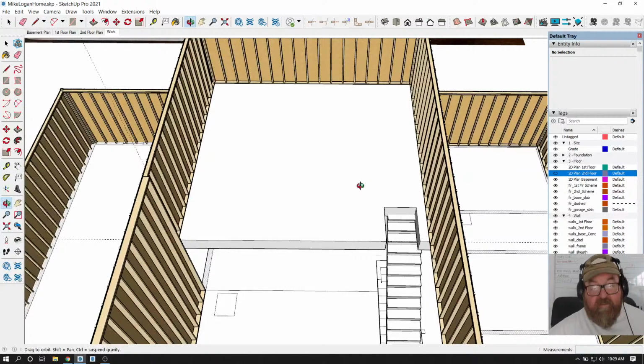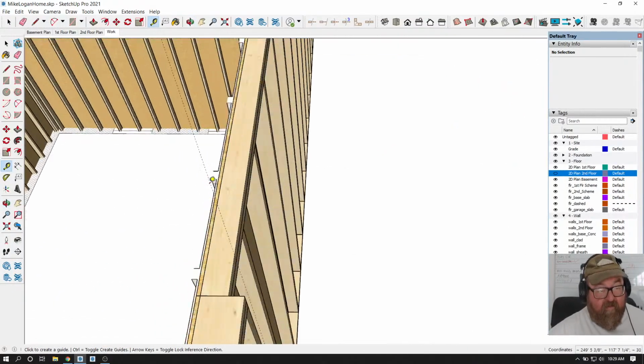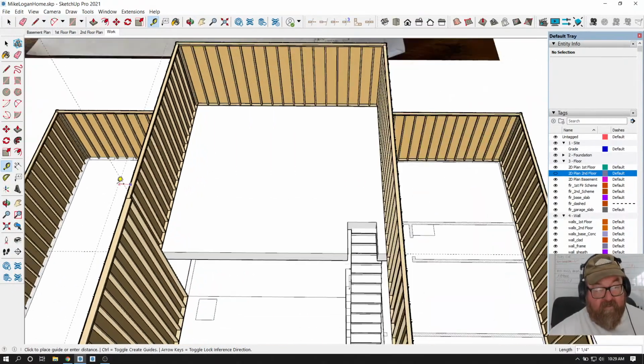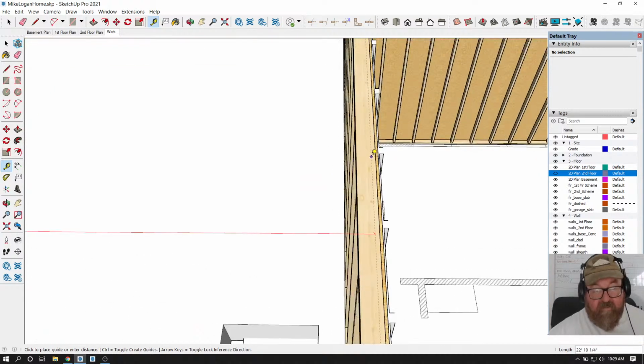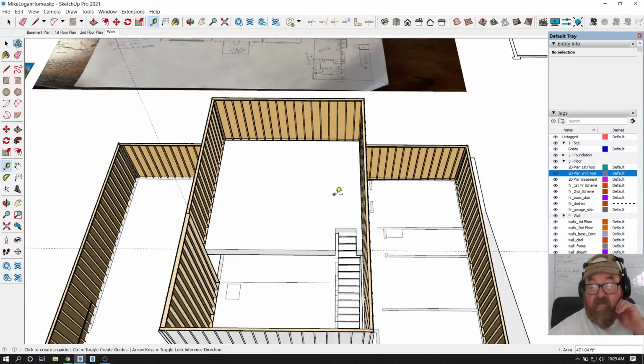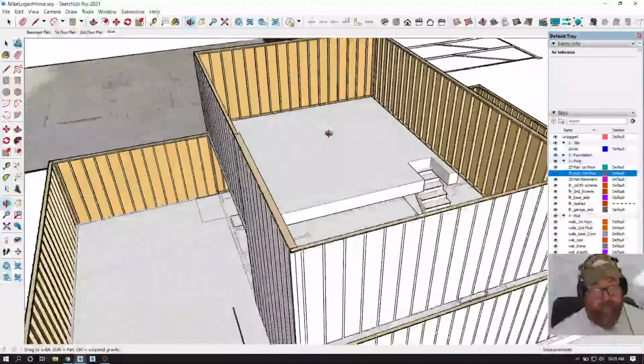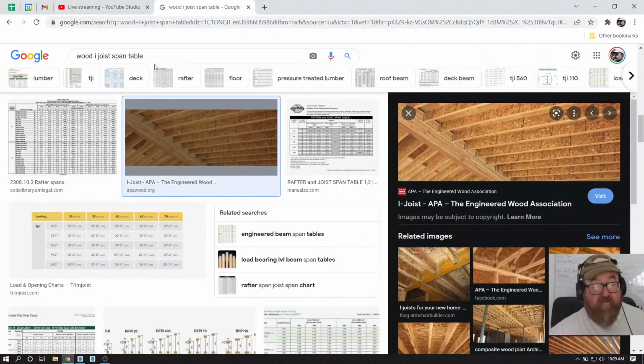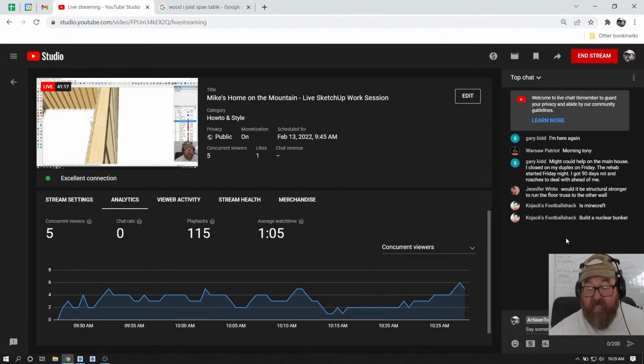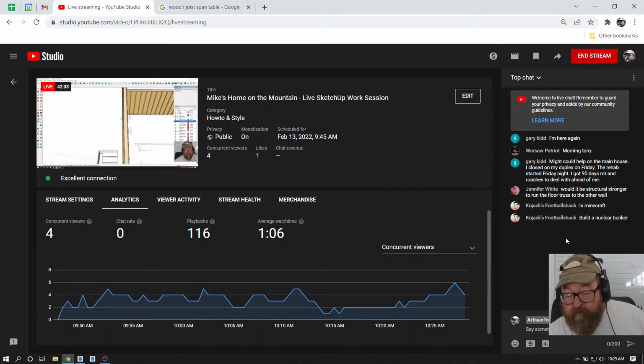This is only 23 feet, and that's not even the actual span. If you go to the outside of the sheeting, it's 23. So I have no issues here with spans. I like trusses, but they're expensive, and it takes 8 weeks to get them now.